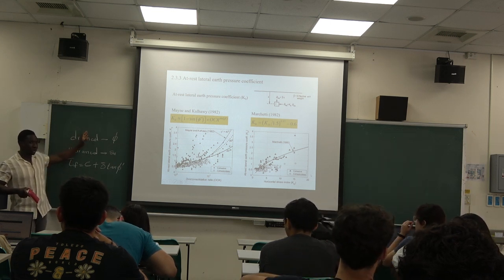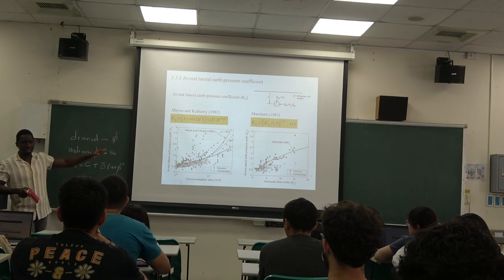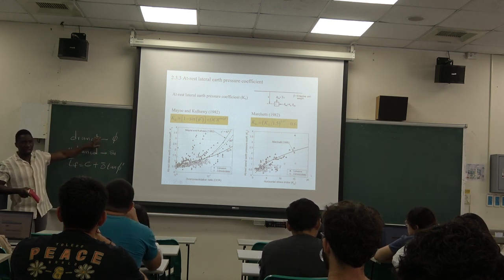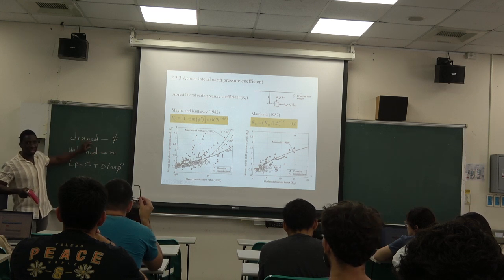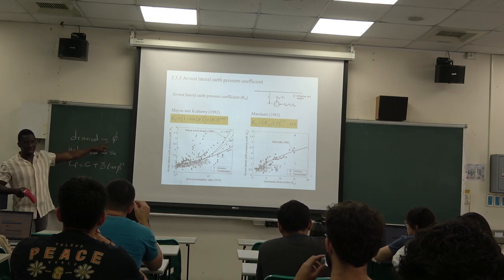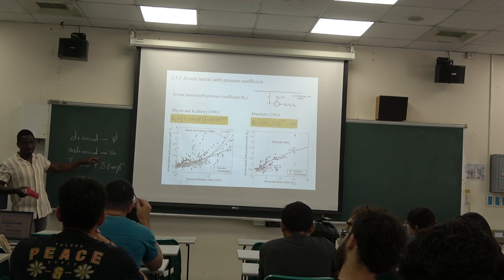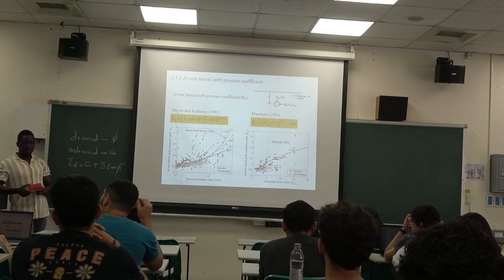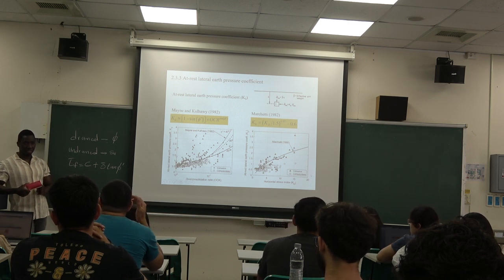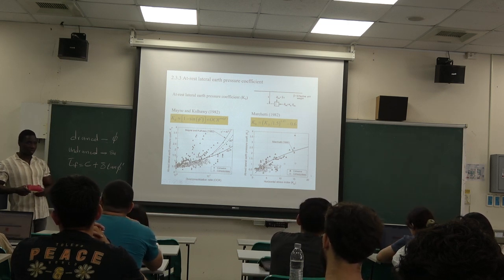They will probably not give you everything. You might have the N, the SPT N value is this. So you need to go back, look at the other formulations, then derive this friction angle by yourself, or maybe the SU value by yourself. So if you have the opportunity, you can think about doing an internship while you're here. It will give you a lot more opportunity to learn.